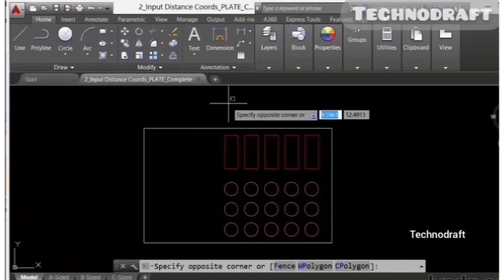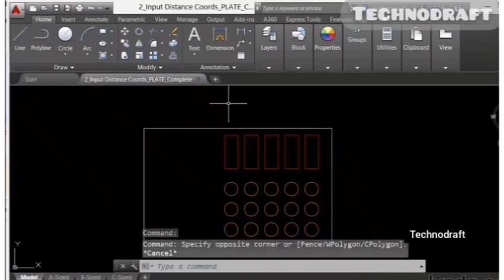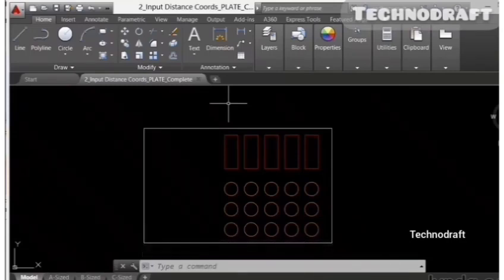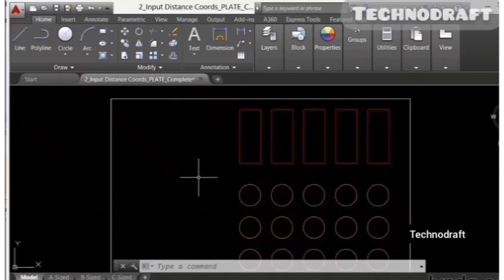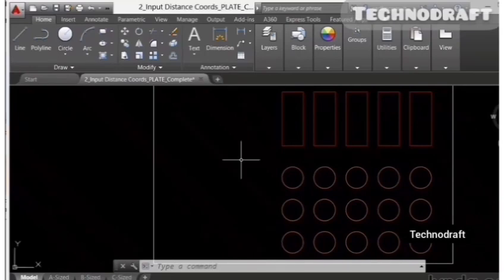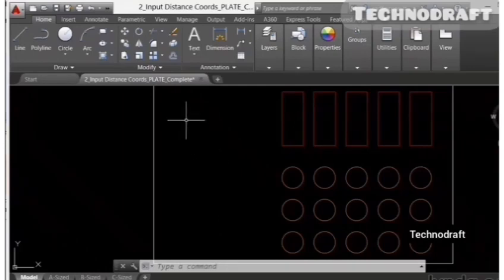And then we are going to draw some lines using dynamic input, direct distance, and coordinates. We are going to have a look at all of it. So zoom in a little bit so that you can see this panel on the left here. I have zoomed in nice and tight, so I can see this panel on the left, and we are going to place a new panel opening in our plate, using the lines layer as I mentioned earlier.